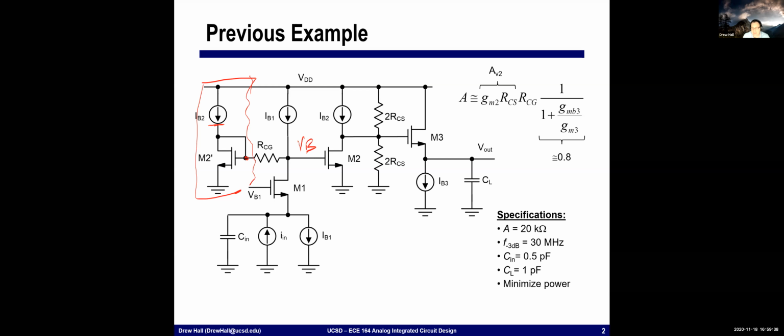And so when you're biasing up the folded cascode, I would do the same thing. I would use one of the magic battery circuits that we've talked about in lecture 6 or 5. But instead of mirroring around the currents like I do in the project, I would just put an ideal current source and be done with it.